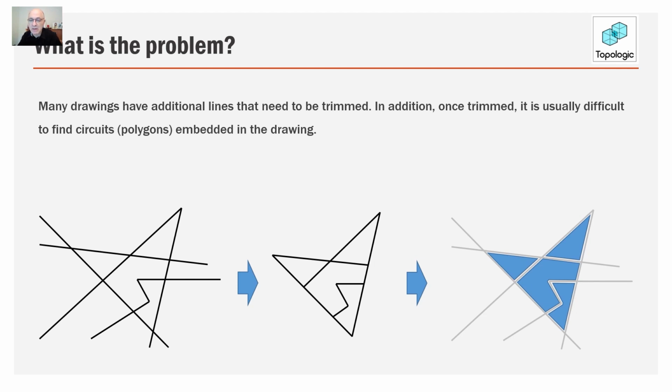It is not a new problem. When I was at the University of Michigan doing my PhD, the researchers there, Ted Hall, Jim Turner, Harold Borken, they were working on these algorithms 35, 40 years ago. So these are not new algorithms, but it's good that we bring them back and put them in Dynamo. So the problem, as you see here on the screen, is that you might have lines that are extending, they are not intersected. So what you want to do are two things. You want to trim the loose edges that you see here, what I call non-manifold edges, and so you create like a clean boundary kind of representation, and then derive the closed circuits from that boundary.